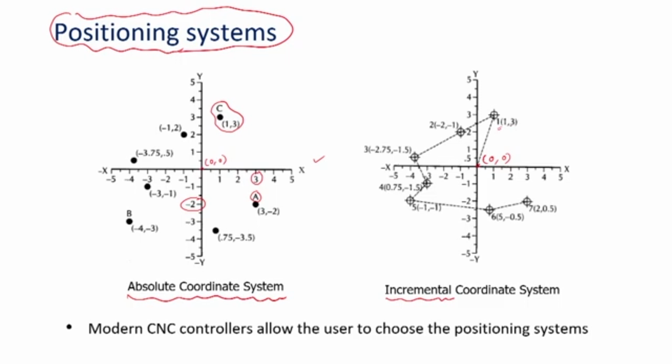So it will go down, and so we got the point number 2 over here. Then we have to specify the coordinate of point 3, that should be with respect to point 2 only. So in this method we are specifying the coordinates in an incremental fashion with respect to its previous location.